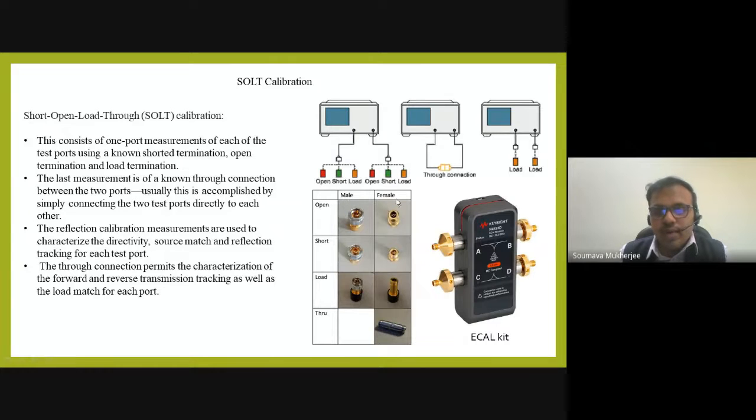There will be male and female versions of these circuits. By means of that, this hole, whatever you are seeing here, will be different. In one case, the pin will be coming out, and in the other case there will be a socket to hold the pin. So depending on which pin your device has, that's how you have to select. If your device has a connector with a socket to hold the pin, then you have to use the male type of open short load through. Otherwise, you have to use female.